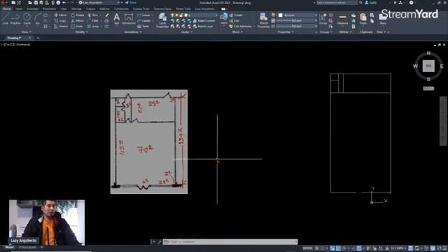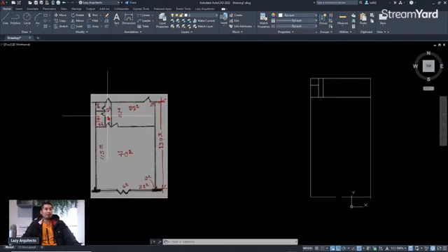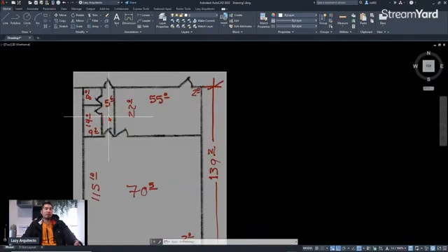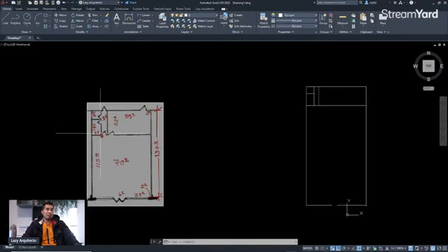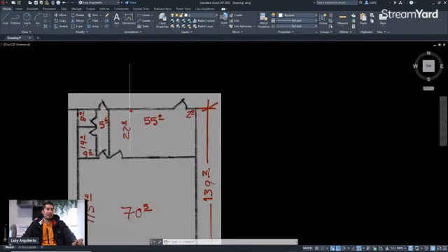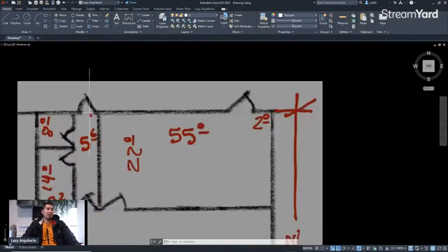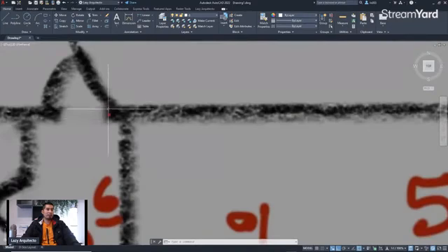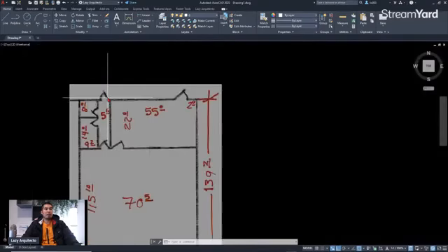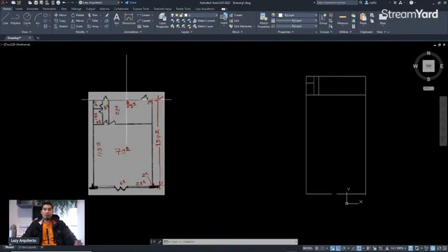Okay. So what's next? We have to give thickness to these walls, right? And the standard interior wall is about 5 inches. So we're going to apply 5 inches thickness to these walls. And for the exterior walls, we're going to apply 12 inches, which are standards, right? Of course, here they are not giving us the wall thickness, but we're going to use 12 inches for the exterior.